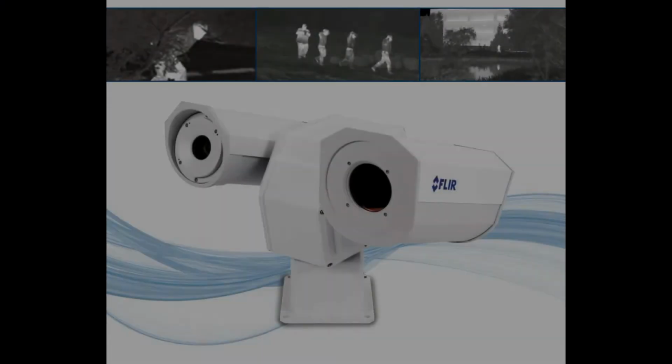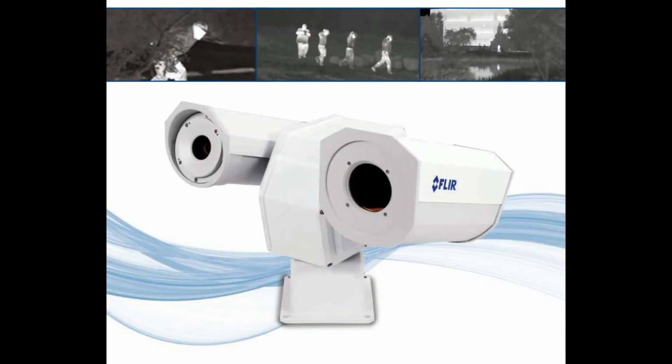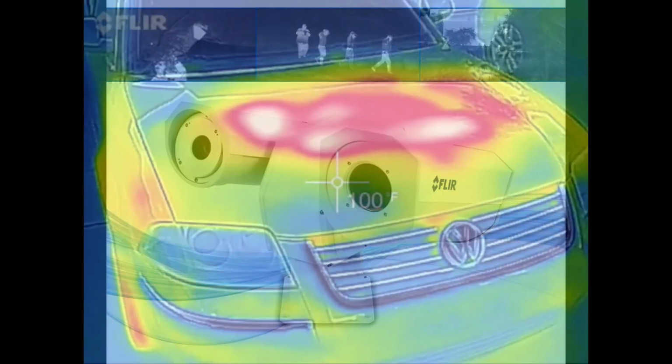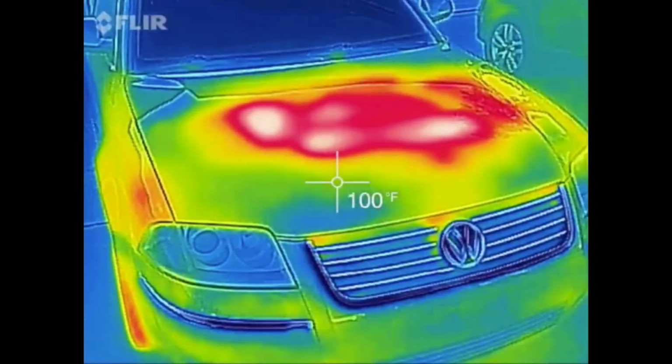The hotter the body, for example a living human being, the higher the energy it will produce, which the thermal sensor picks up as brighter light. Basically, the thermal sensors see like a black and white sensor, which the camera software then maps each different intensity to artificial colors in order to indicate which part is hotter.